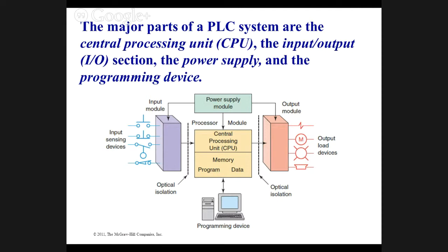Those inputs go into what's called the input data table. All right? And from the input data table, which is just a binary storage location, it goes through the program. When the program finishes scanning, it updates the output table. Once the output table is updated, it sends that information out to the real world, to the card. Okay? That all happens really fast, milliseconds.